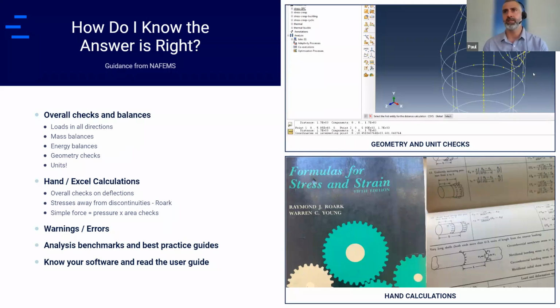And it's a very simple error, especially for younger engineers. But if the units are right and everything is consistent, then it makes things very easy. And for doing stress analysis, I would generally tend to prefer to use millimeters and megapascals. It just makes everything work a little bit easier. The other thing that I recommend